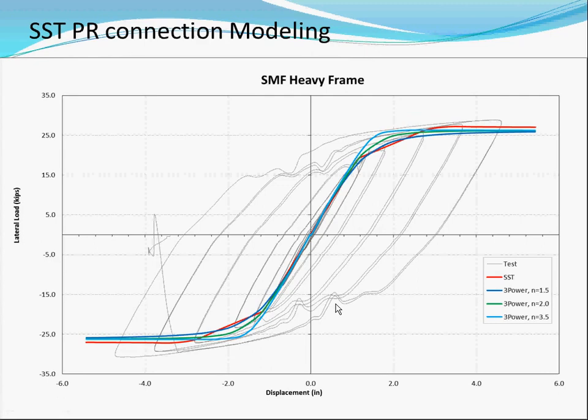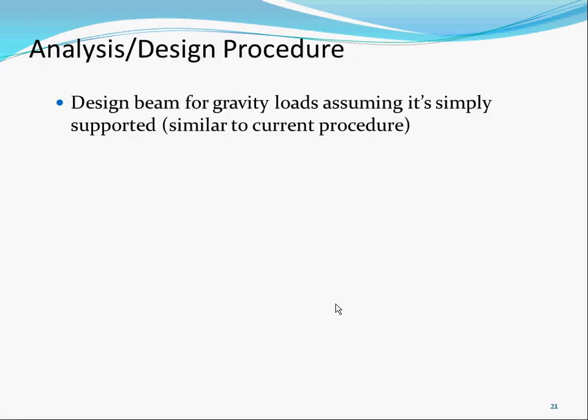That's why we know we're using heavy in the line, the medium. That's how we named it for the testing before. Right now we're not offering the medium. Previously the testing was the light, the medium, and the heavy, and how we came up with that was based on the thickness. Remember 0.25, 0.375, and 0.5. Because of the buckling of the lighter ones, we're just restricting everything to the half an inch because we didn't see any buckling. So right now, T-link is only half an inch, heavy, until further testing. But remember, we could neck this down to whatever we want.